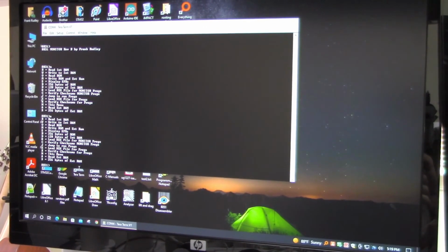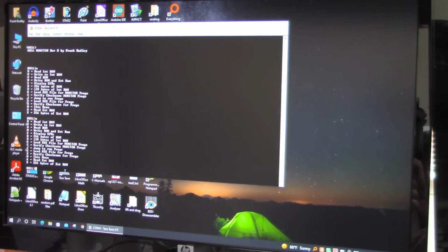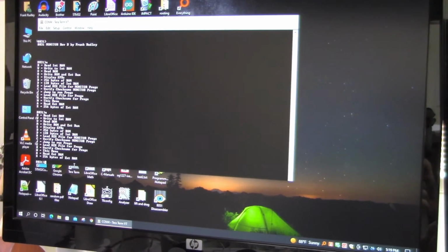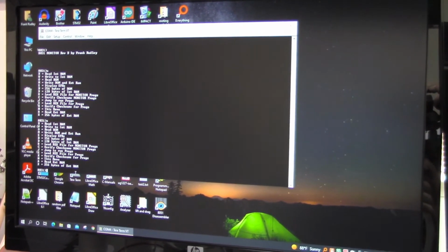So the one program I run, I type a J and it jumps to 800 in the user ROM. So I'm going to trigger off of that, because that's where my program starts. I'm going to do that to try to capture the code that's going into that processor.